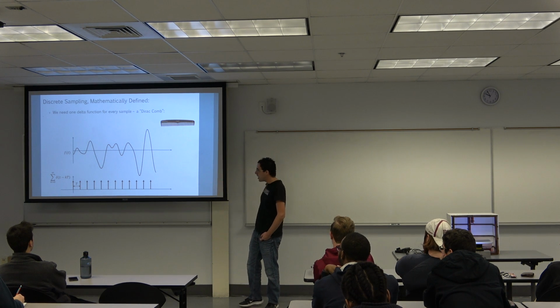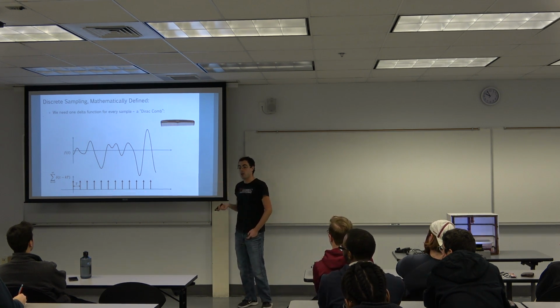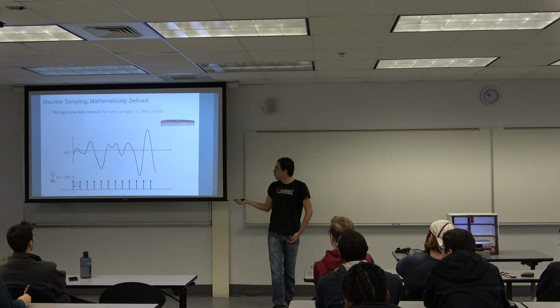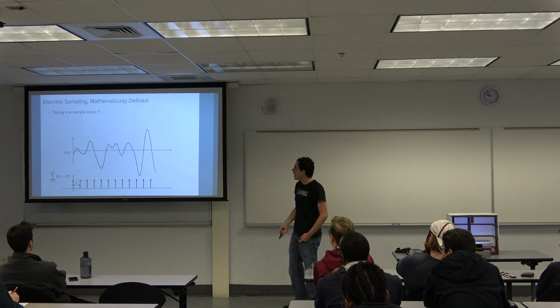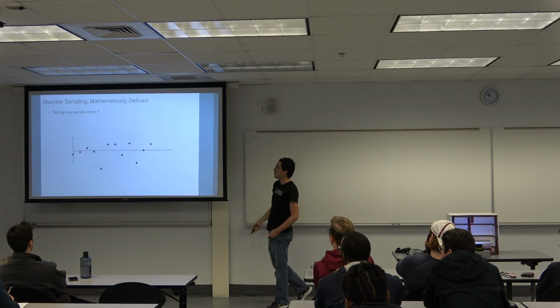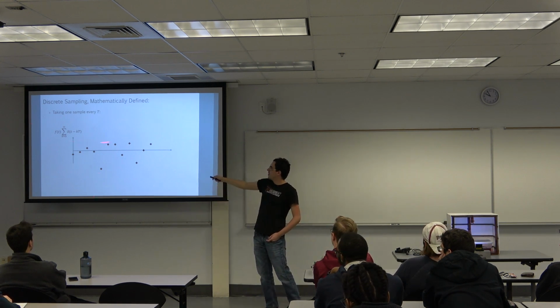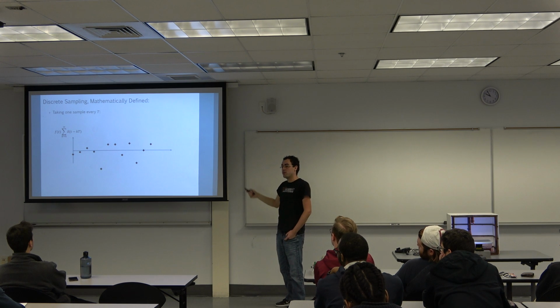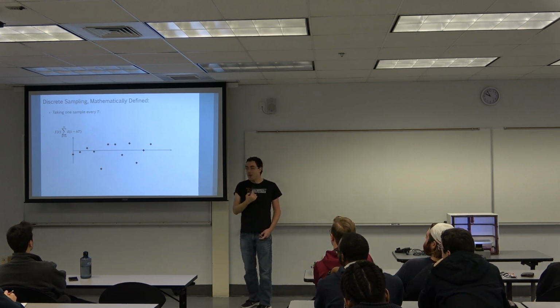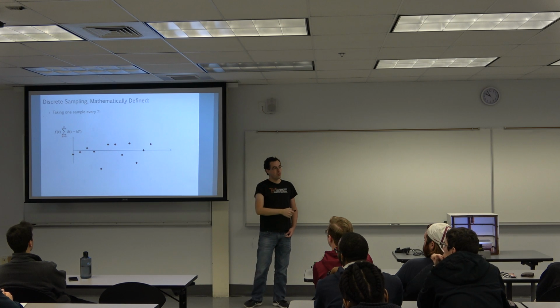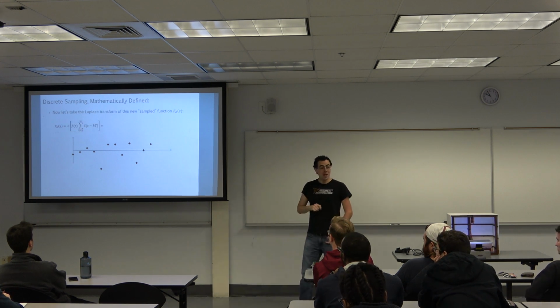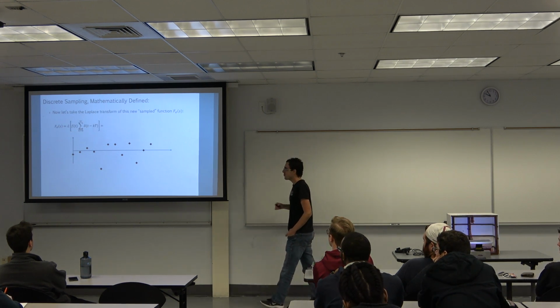and we do that however many samples we want. And if we multiply the delta function, or the set of delta functions, by our continuous function, we get several samples. And this is how it looks mathematically, it's just a multiplication of the two. And the cool part is now we have a function to work with. So we can take the Laplace transform of this function.